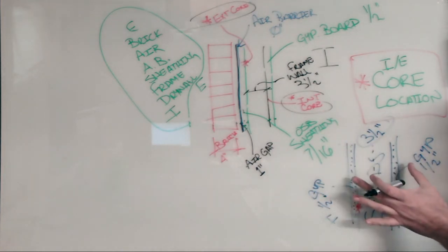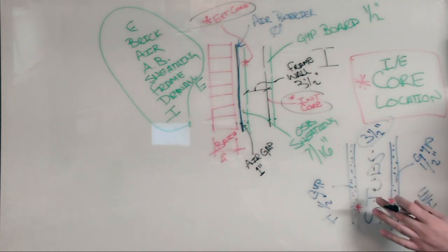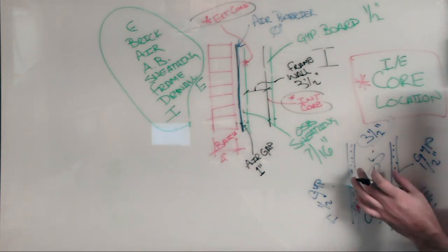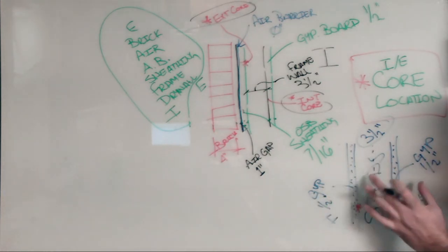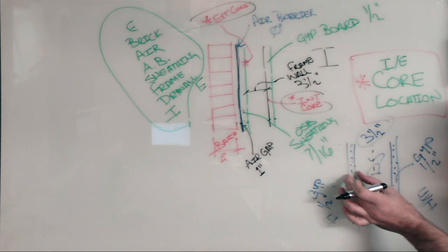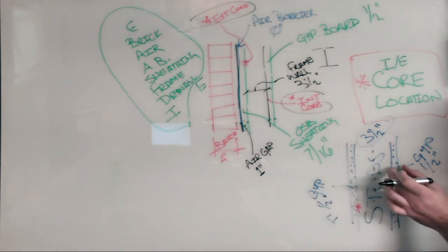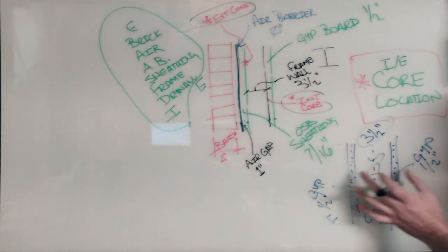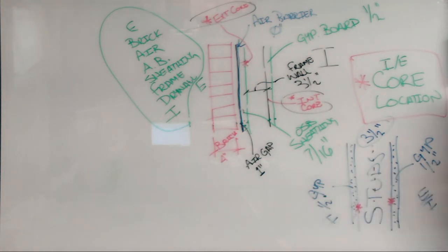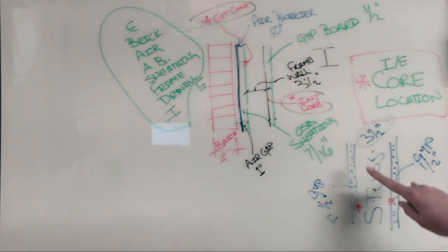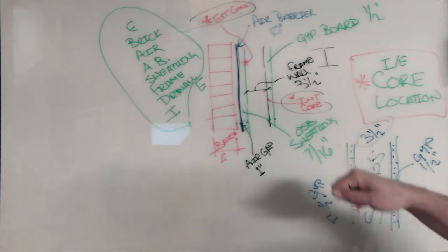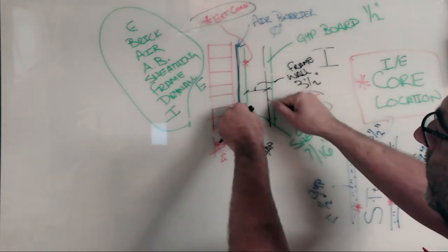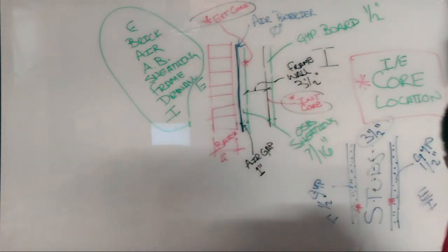So on this one, probably technically not an issue. You could either choose wall center line or you could choose core center line. I always tell you to spend time using the core center line, because if we had to go back and modify this for some reason, and this had to go to 5/8 inch drywall, but this one had to stay 1/2 inch, your walls wouldn't shift. And if you had it on the other one, it would shift. Okay, so we've gone through wall center line, which is out to out, dead center, and then we went core center line, which are our identified core lines, the center of those.